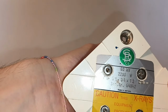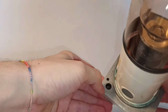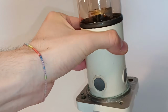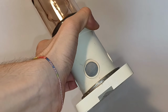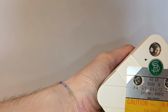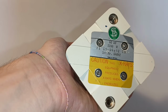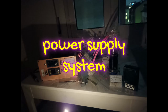And because it has this much power, you can see that there are 2 holes here and here, from which cold water is being circulated, coming inside from one and coming out from the other side. Water cools down the anode and prevents it from overheating and then melting, and then fusing the base of the tube, which then would implode and destroy itself. The other tube didn't have a system like this because it runs on less power, maybe 1000 watts, but only for 1 second, and doesn't produce all that energy that needs to be dissipated.